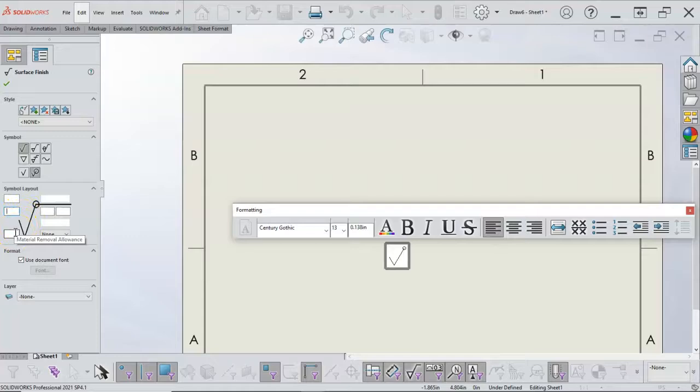Highlighting material removal allowance. If I was machining this to go to a grind, where I wanted to go finer than a 16, getting down into the eights, I might put this on a surface grinder and machine to a higher tolerance limit. So if it's a half-inch piece, maybe I would machine it to 5 thousandths over, so I don't have too much material to grind, but it's within the flatness and the ability of the grinder to remove that material.